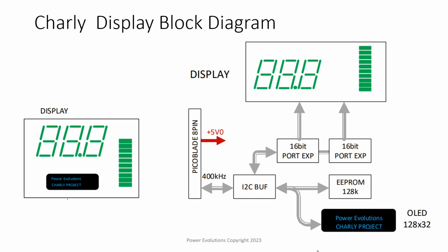I'm going to figure out what I'm going to display there; I'm not sure yet. The main speed of the bike will obviously be displayed on the 3-digit display. This is interfacing with that ARM processor through an I2C bus. And all the information that was collected on the ARM is available on a CAN network.